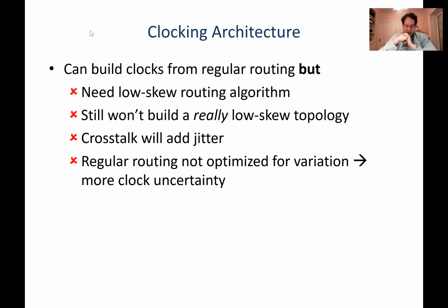The next thing is another source of clock uncertainty. So jitter is a form of clock uncertainty, which, as I said, hurts your timing for both hold and setup. The other source is variation. You don't really know exactly how fast any one transistor is. You don't know the exact capacitance of any one wire. FPGA timing models actually assume, again, the worst value. Would a fast value or a slow value hurt me on this kind of analysis? And they'll assume the worst value that could happen on that chip.